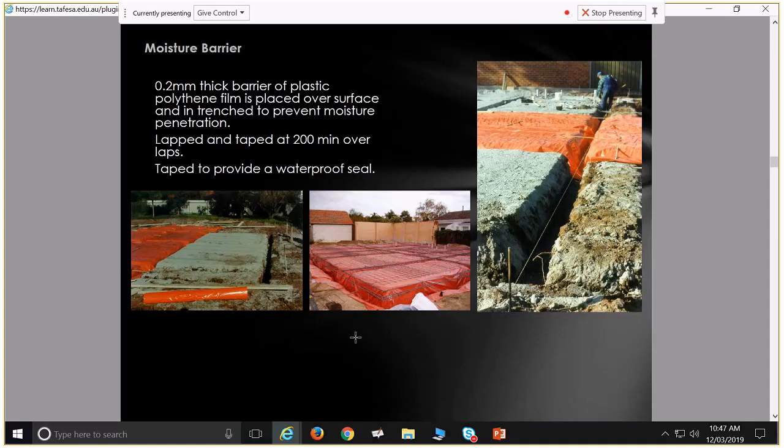Other termite protection is things like crushed granite. Termites don't like to burrow through tiny little bits of crushed granite, but of course, you've got to be fairly thorough with the application of that as well. Another way, it's not termite treatment, but you can build it all with steel or hardwoods or something like that as well.